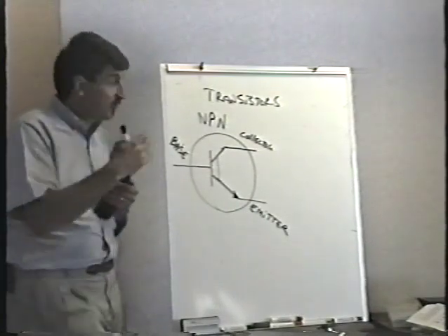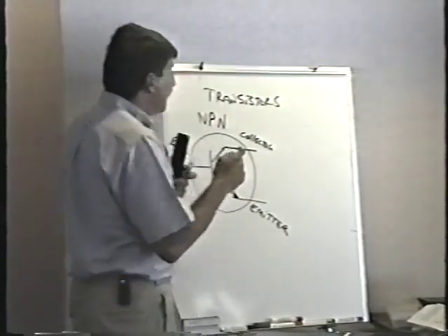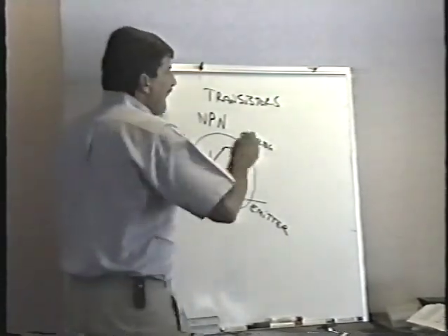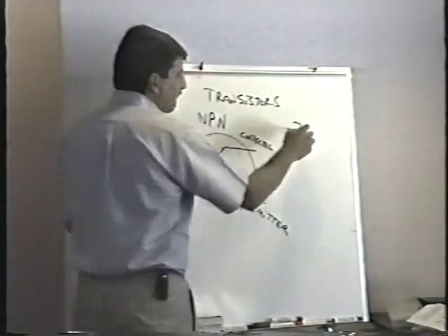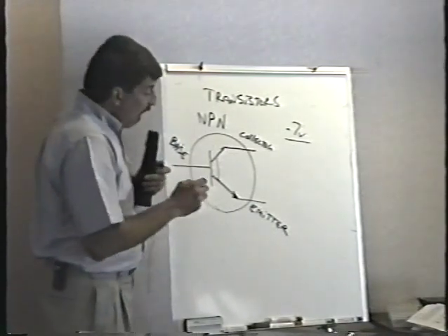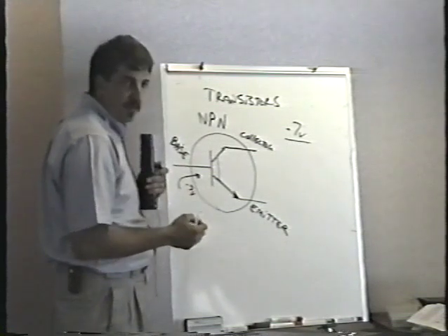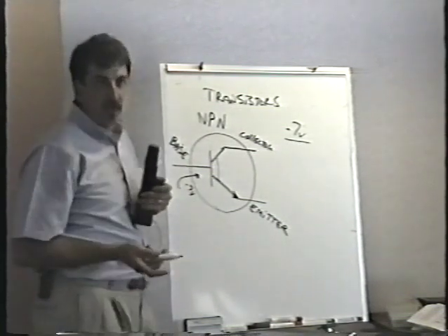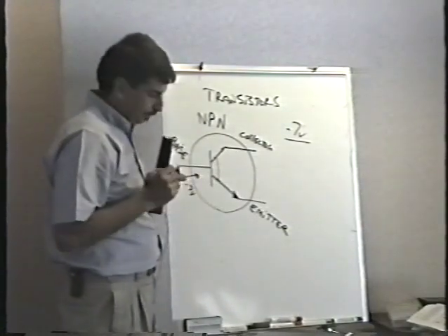Remember that 0.7? Remember I said it takes a certain amount of voltage to operate the diode, that junction drop? Same thing with transistors. That 0.7 is like a magic number that we get to again and again. That's 0.7 of a volt, because that's how we turn the transistor on. All I have to do is put 0.7 of a volt on the transistor, which is an itty-bitty amount of voltage, isn't it? And the collector and the emitter connect together.